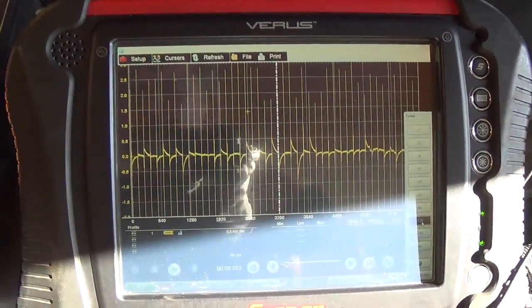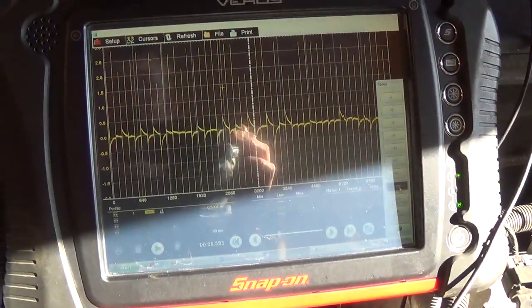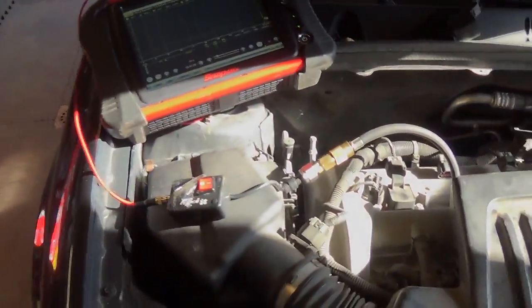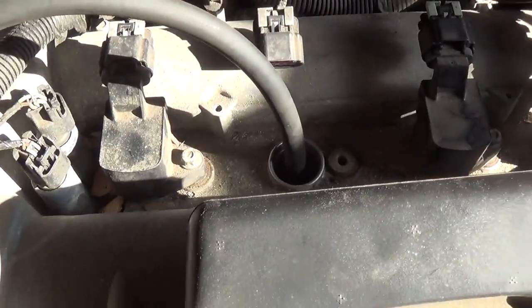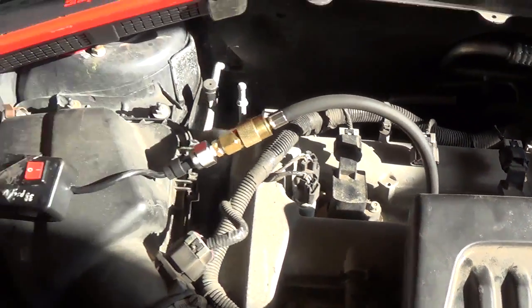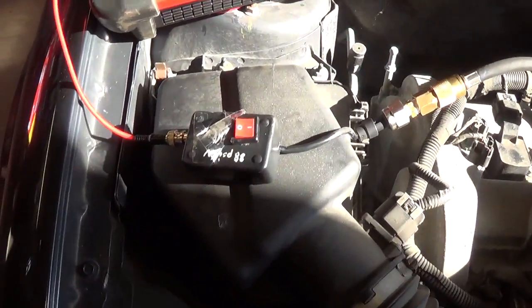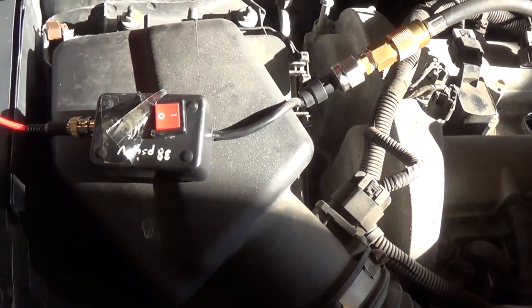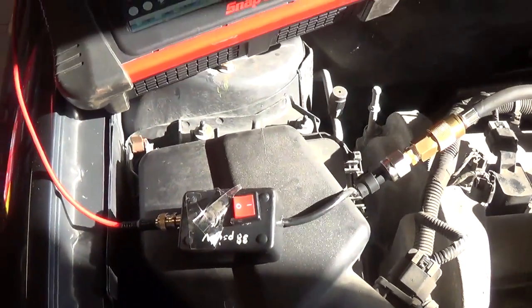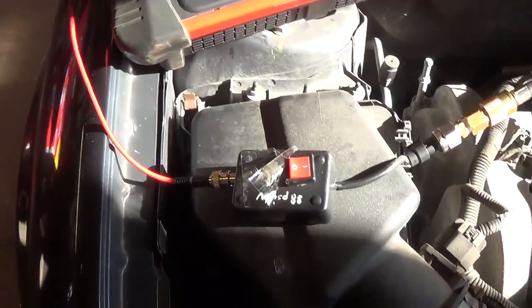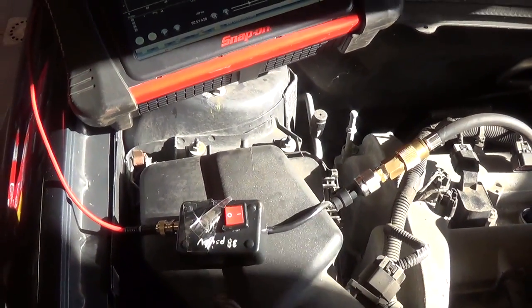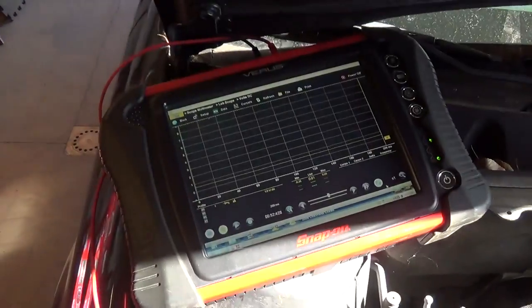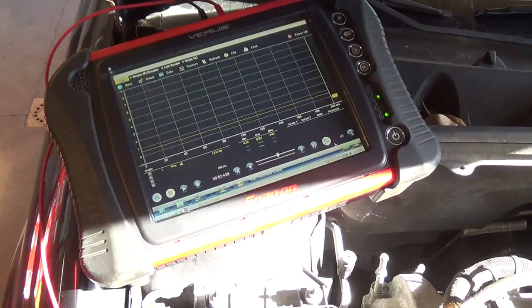Let's do something more fun, the pressure transducer. Alright. Pressure transducer, cylinder number 2. It's a known good. Here's our homemade version 1.0. I actually modified it yesterday for this case study. I installed a 5-volt regulator in there, so now our calibration should be a lot more usable.